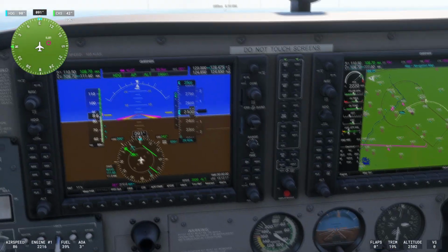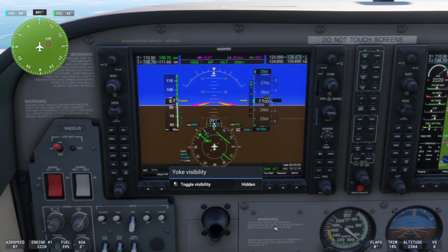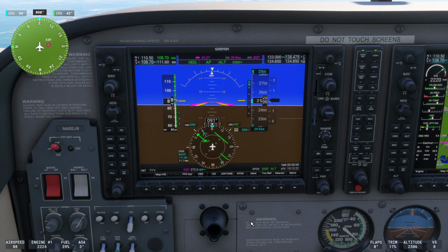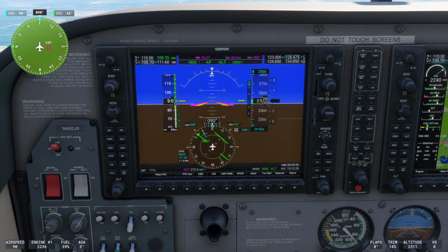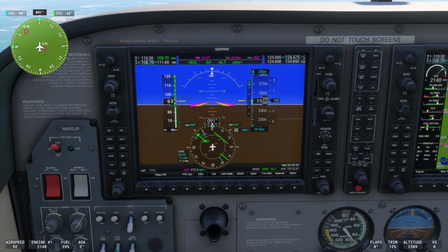All right, so I have loaded up here a Cessna 172 G1000 model, not unlike what you'll probably be flying. However, this one actually does have the physical ADF and DME capabilities installed in the aircraft. We're not just using GPS and substitution of it. So basically to start off, we're just going to shoot the ILS-4 approach using ADF and DME as God intended, so to speak. So we're not using GPS to substitute for it, just to show you what it's supposed to look like. And then we'll compare that with using GPS substitution and how the two will differ throughout it.